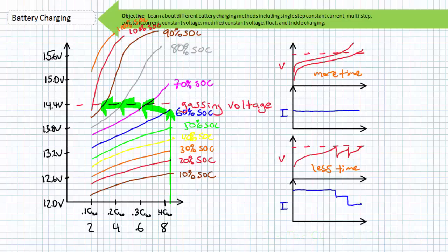Thus far, we've discussed battery charging only in terms of controlling current. However, voltage is an equally important property since it is the factor that directly determines current magnitude. At a very basic level, a constant voltage source could be used to charge a battery. However, this method isn't ordinarily recommended since excessively large currents can damage a deeply discharged battery.